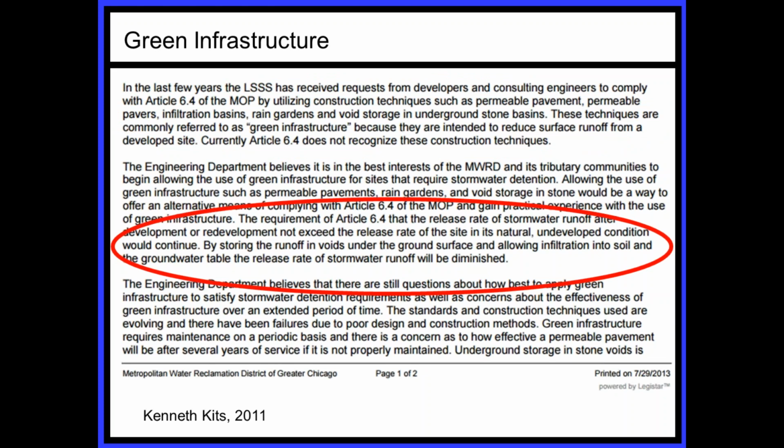They went on to say that what their goal is, as I mentioned a little earlier, is that one of those primary goals is to encourage infiltration down into the groundwater system. And essentially, what we're talking about here is volume reduction. So you have a 1-inch rain on a site. The goal is to let as little of that 1 inch over that surface area leave the site. Obviously your goal would be to have zero leave, but often in urban environments that's not practical. So we look for something kind of in between, generally speaking.